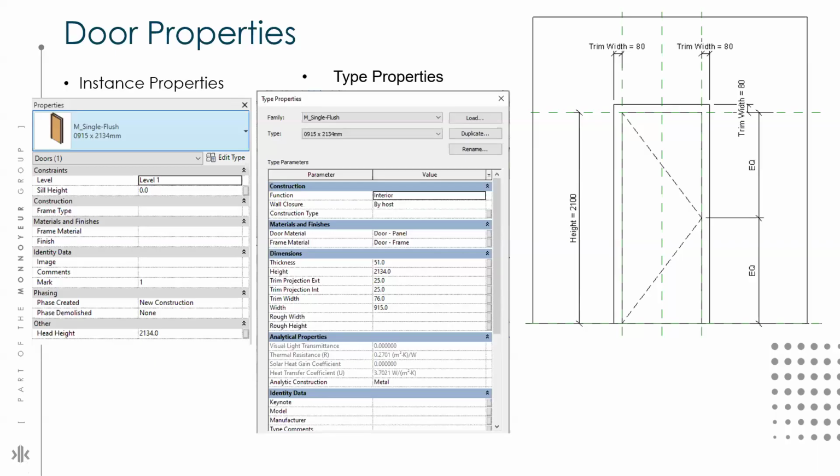That means that if I place this door and then add a door tag, it will give me the symbol as 1. So to change it to D1, I can simply change the mark in the properties panel to D1, and the tag will also appear as D1. I hope that is clear. That is for another session, but just because it has come up, I am discussing it.